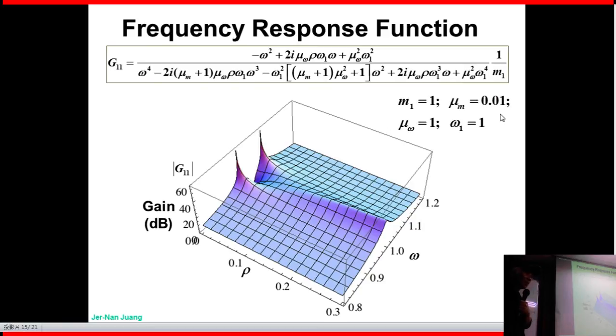Agree? Your TMD mass at the top of 101, do you think you want it to be too heavy? No. This is why I chose 1%. 1% means my TMD mass is only 1% of the whole building of 101. That may be too heavy too.